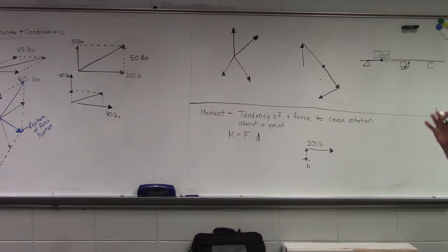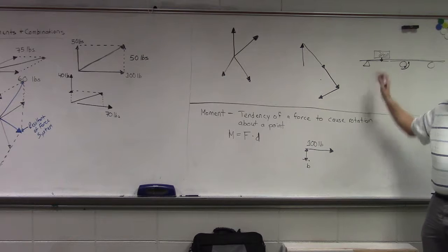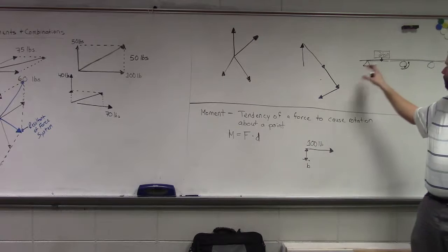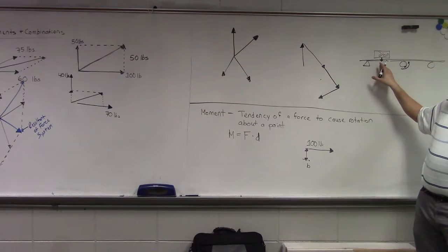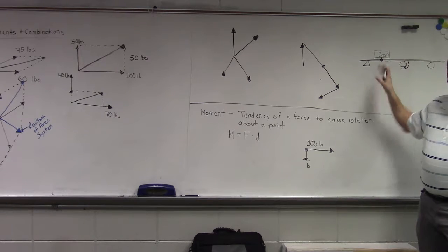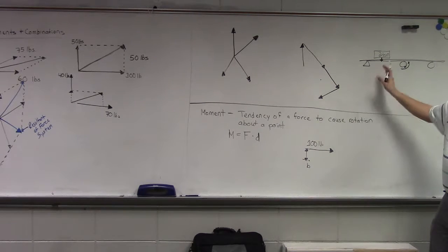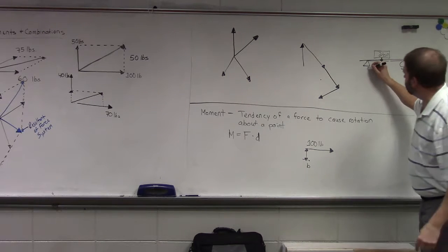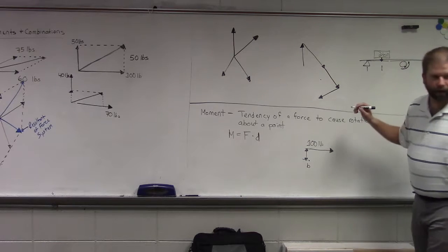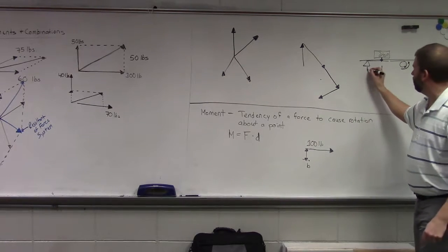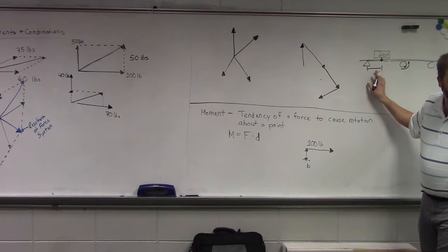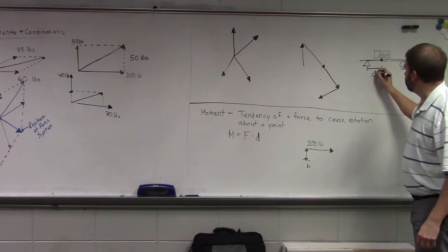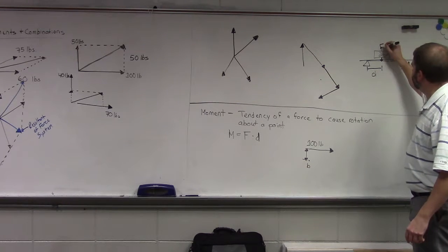We'll look at some uniformly distributed loads as well, but let's consider our truck, instead of being 53 feet long and applying that 2-ton load, well, it wouldn't be applying 2 tons if it's 53 feet long, so we'll say 20 feet, right? Instead of distributing that over the 20 feet, we'll just say it's 2 tons being applied at this point, okay? So you would determine how far away you are from your reaction. This is your distance that you use. Here's your D, here is your F.